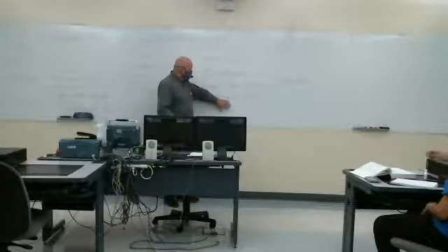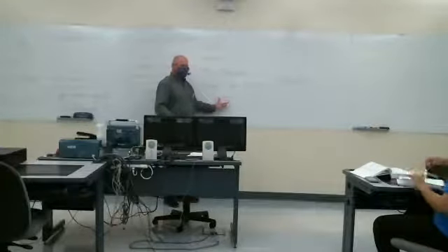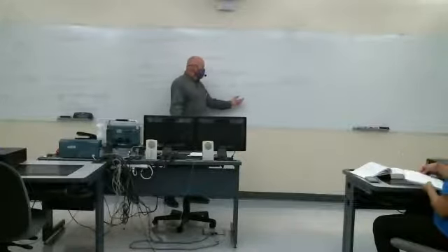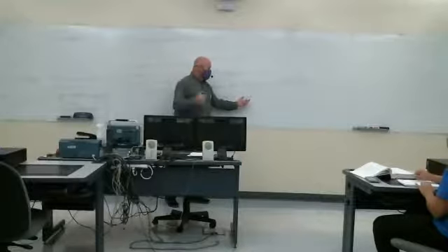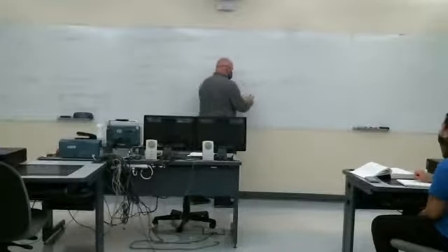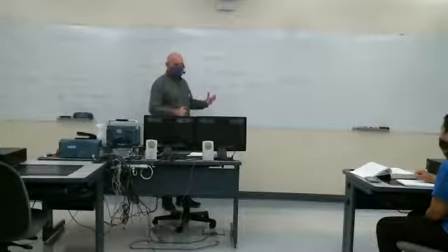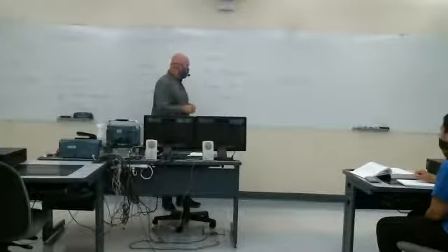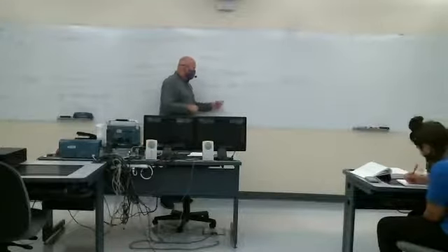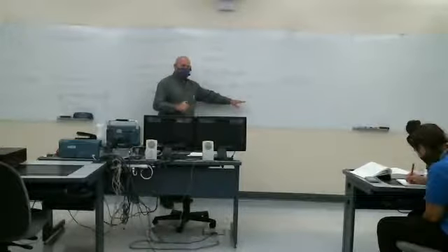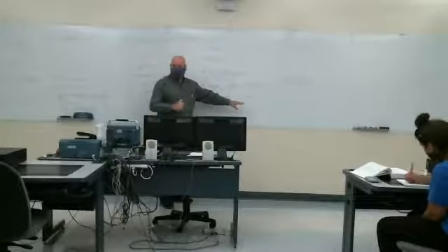It might help to call this a new signal, maybe W of t. W of t is equal to Cx of t. Then what I would get out here is 3 times W of t minus capital T, and then substitute back in that W is actually equal to C times x of t. So this is the response I get due to the input scaled by C. Okay.